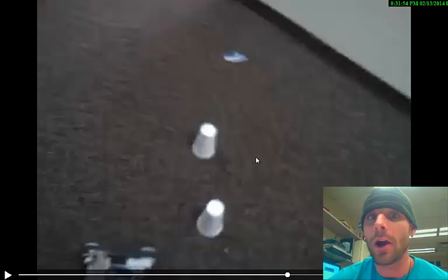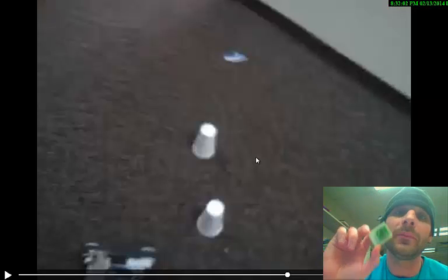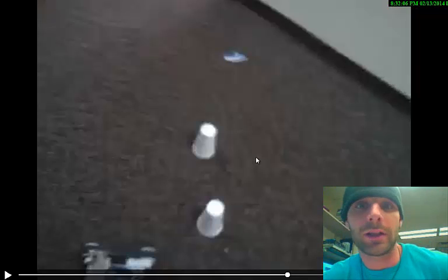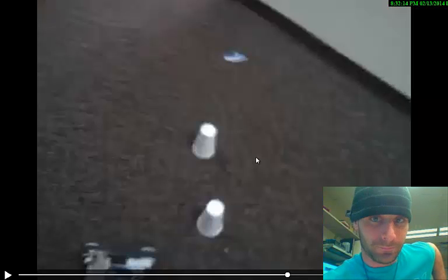Localization is a very hard problem for robotics. It's one of the biggest things I've struggled with here. What I'm doing right now is called dead reckoning localization. I'm using 2 compasses and some type of filter to reduce the noise in those compasses, and I'm using the encoders built into his motor to get a linear vector, and then use the linear vector and the orientation bearing and some trig functions to calculate an XY position.